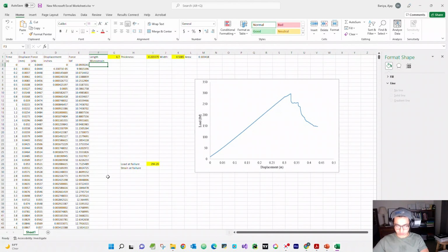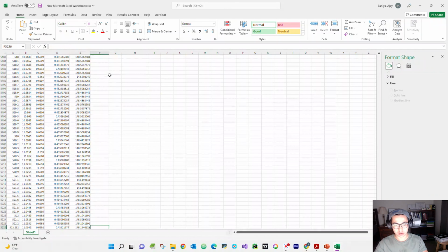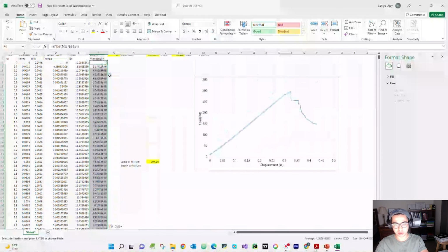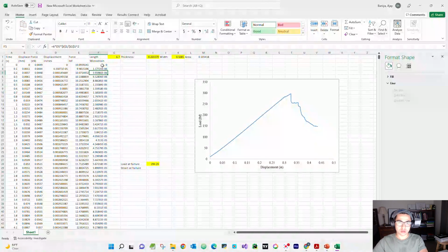So from the formula that we defined before, it's going to be 6 times displacement times thickness divided by L to the power 2. And let's put a dollar sign in here because I have to copy them to the overall page. So basically let's go down there, type something, go up and copy that and paste it over here. So this is in strain.